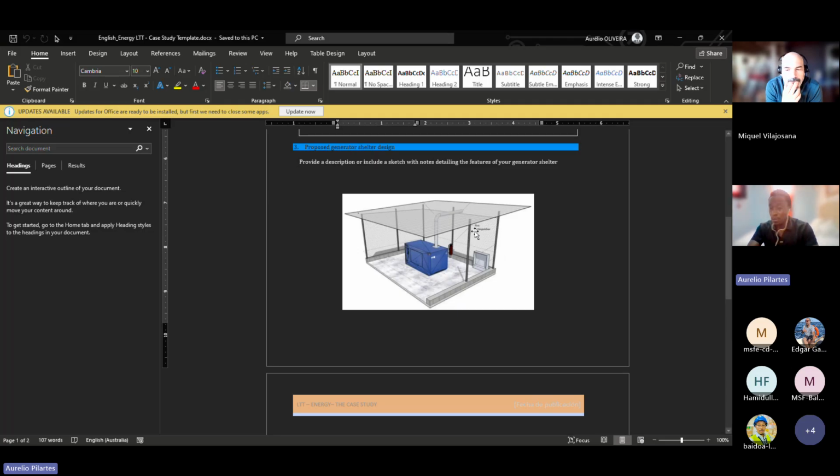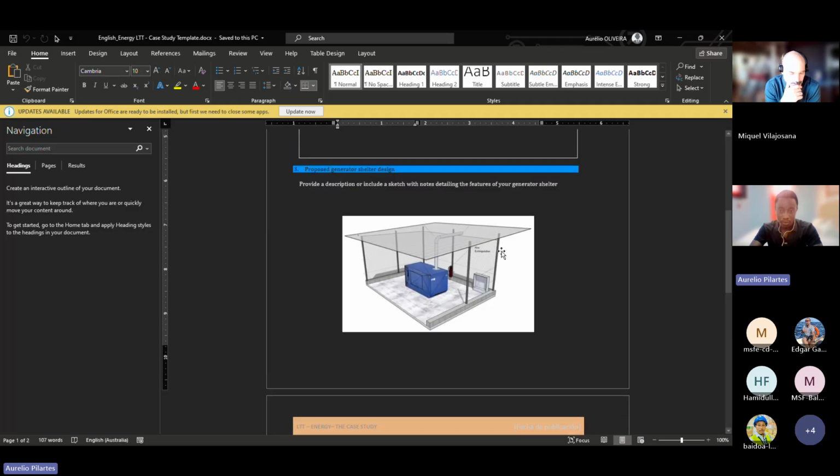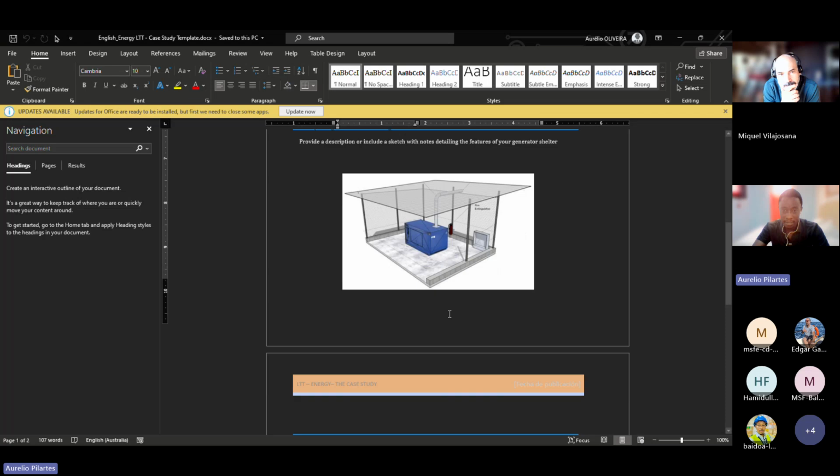Anyways, whenever you can, it's always a good idea. It can also be a good idea to do a proper house with a wall and everything. But as long as you have enough space for circulation, so your generator doesn't heat up a lot. There are also constraints on the spaces you should leave between the generator and the walls. And then you should always have this pipe here for the exhaust of the generator. So all the smoke and the exhaust of the generator will go out of your house.